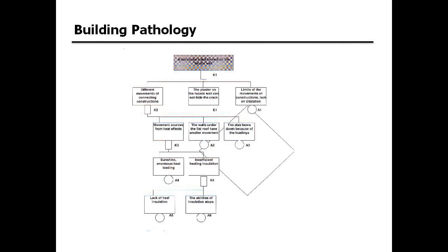So these are questions that always need to be asked to see whether this issue of deterioration is an isolated incident or whether it's something that may be impacting the whole of the external facade of the building, and that we need to make further allowances and further audit or further investigation so that it doesn't create a bigger problem, a bigger liability for the overall building, as in cost, as in downtime, as in, again, possible loss of tenancy or possible loss of use of the building.